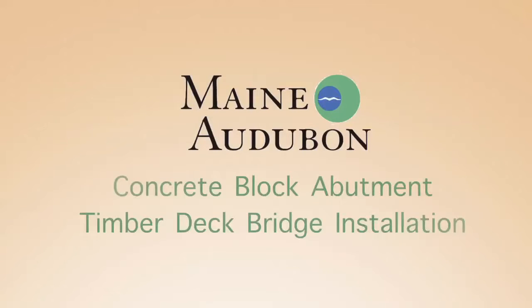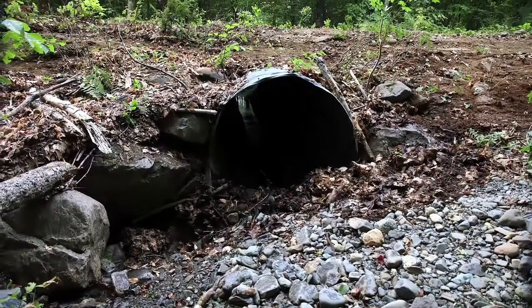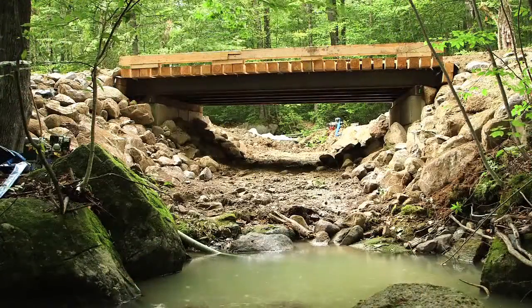In this video, you will see the construction process for a concrete block abutment timber deck bridge installation. All these projects are replacing failed and failing culverts, and a lot of them which were perched, which were blocking fish passage with bridges. A lot of these culverts are starting to fail and they're starting to plug from the upstream end. And for 25 years, the streams up above haven't been used for spawning habitat.